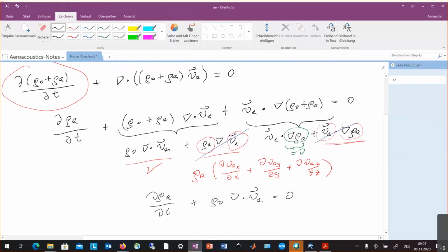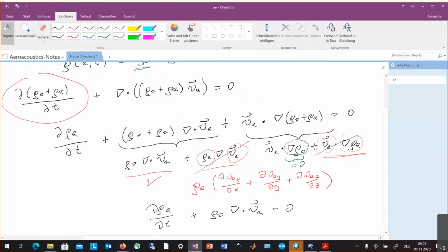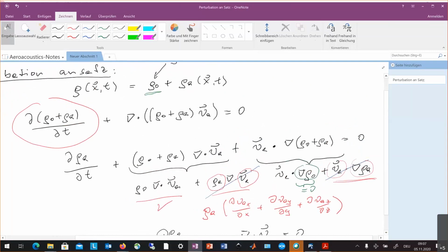Okay, so you see, this is all straightforward, but it is very important that before you do the derivation from the general compressible flow equation, you are sure for which physical effects you do your modeling. And then you know if your quantities are functions of space and time, or just of space, or just of time, or they are really constant.